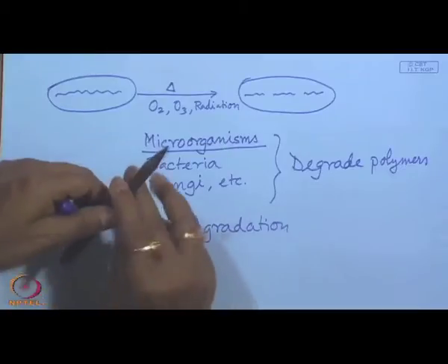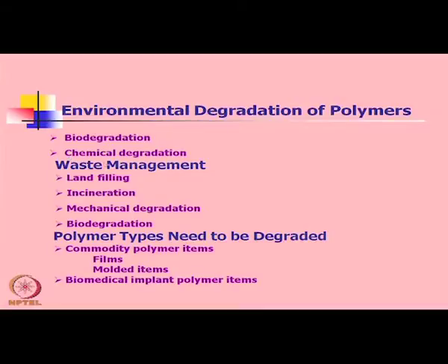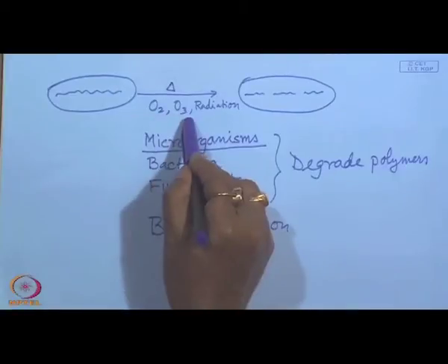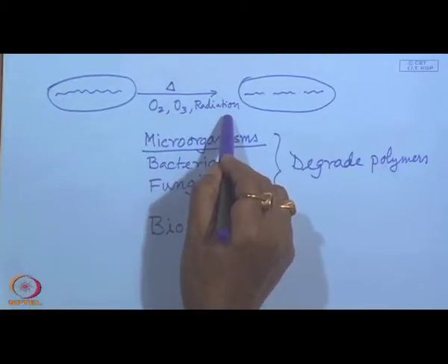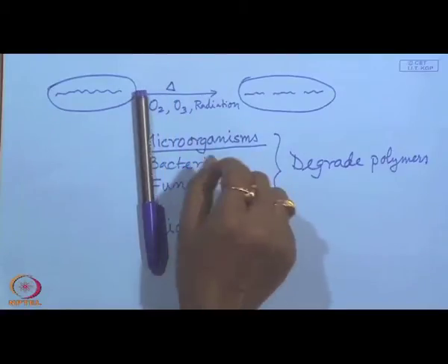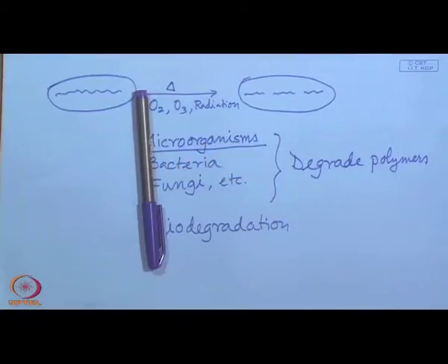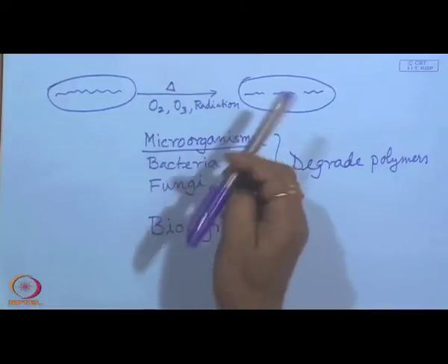Other than biodegradation, the degradation of the polymer can be due to oxygen, ozone and radiation effects, heat effects of thermal influence, etc. So, they also degrade to smaller fragments, and to some extent they degrade into carbon dioxide, and in the extreme situation carbon dioxide and water.